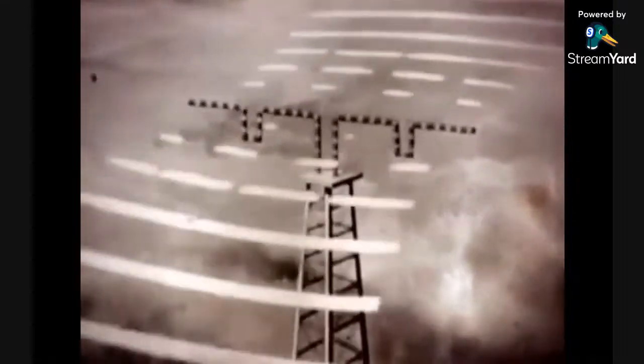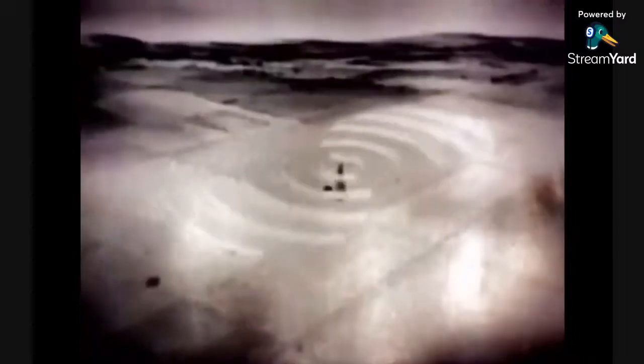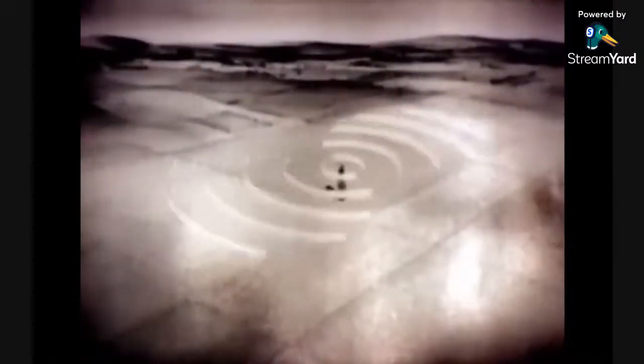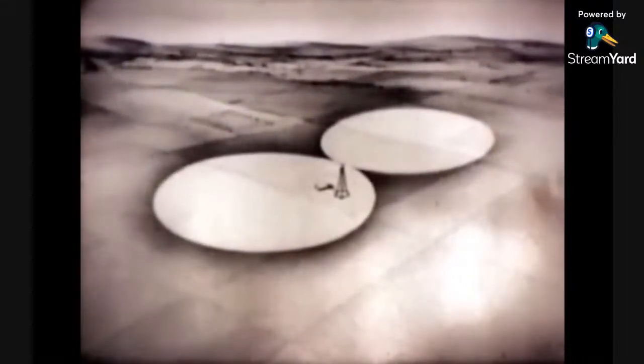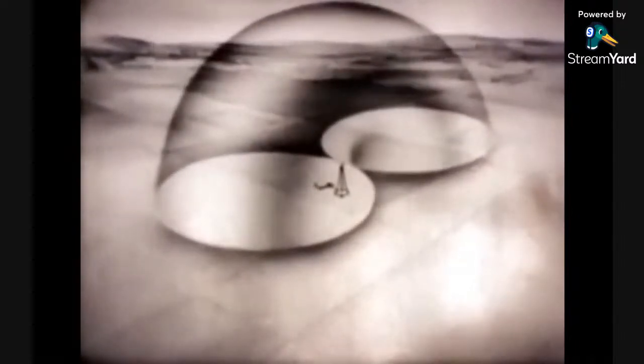Maximum energy radiates from the center of the elements, with the strength gradually dropping to zero at the element tips. The same transmission takes place on all sides of all elements. Thus, the transmitted radio wave pattern resembles, horizontally, two paddles projected from both sides of the array. Vertically, however, the pattern has the shape of a donut.